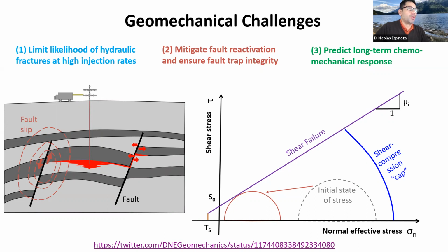All right, so fault reactivation is going to be an example of shear failure. And shear failure is something that, if you already took the geomechanics class, or if you're going to take it, is what happens when you load the rock in triaxial loading, and sometimes also it would happen when you load it in the unconfined compression test, which I'm trying to pull out right now.